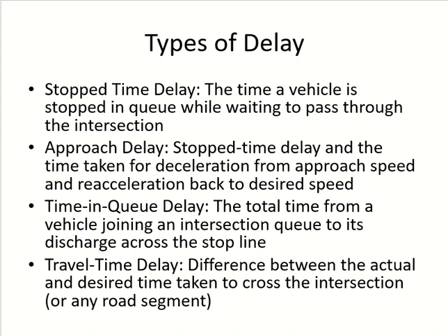If you don't stop, then once you cross the intersection, you accelerate back to your normal speed. Then all of this is counted as approach delay. What other name have we given it? Control delay. Okay, it means the same thing.